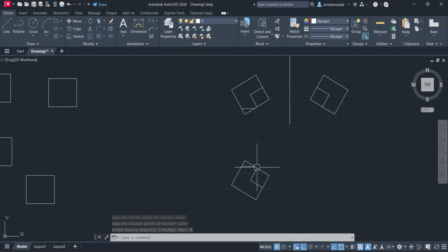So it is not like a line is mandatory. The mandatory thing is the point, so at what point it is. And if you wanted to mirror with a particular distance, that time distance matters. Otherwise, if you're just copying and pasting it somewhere, you can directly go with the ortho mode. No need to create a line.